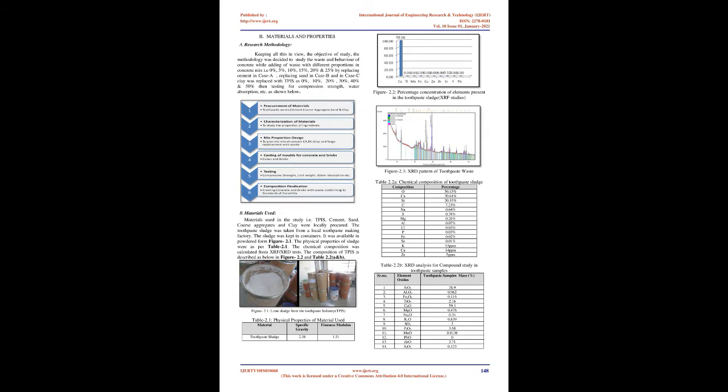Few studies have been performed on utilizing sludge materials in the process of concrete making. Petro et al., 2013, 4 conducted an experimental study for the innovative use of hypo-sludge in concrete formulations as a supplementary cementitious material, tested as an alternative to traditional concrete. The cement has been replaced by waste paper sludge in the range of 0%, without hypo-sludge, 10%, 20%, 30% and 40% by weight for M25 and M40 mix.